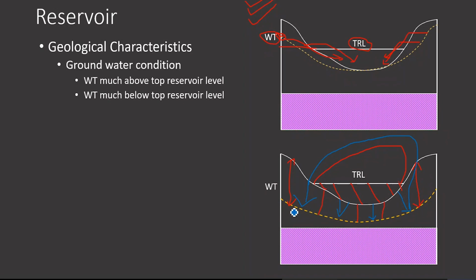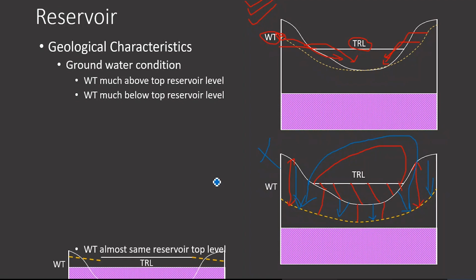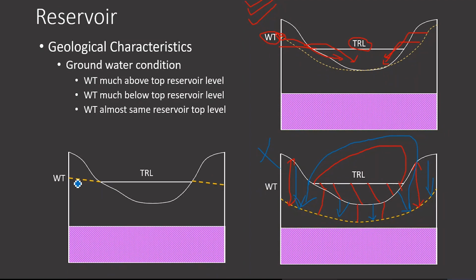It will recharge the groundwater, and this groundwater will be extracted through some other place, or it may travel within the rock, and the movement of water will happen below the surface. And that is not the purpose for which we constructed the dam. The dam is constructed to store the water, and the water is going to be used for some purpose, but it is now being lost into the groundwater. So this is not a favorable condition for the consideration of a dam.